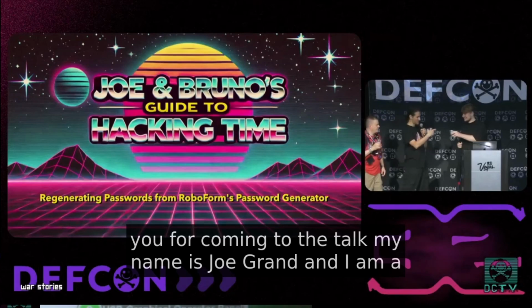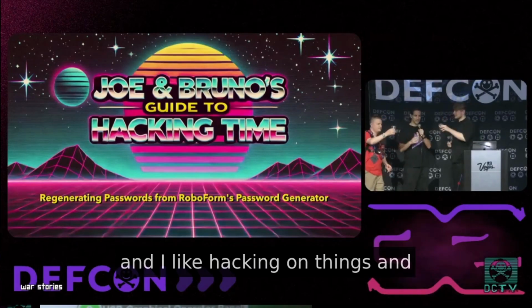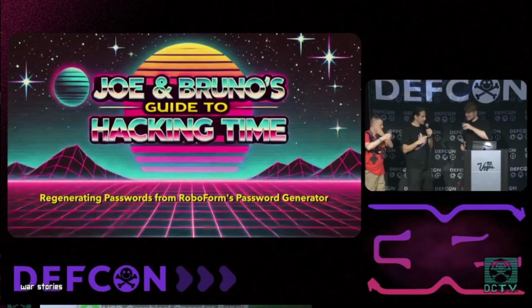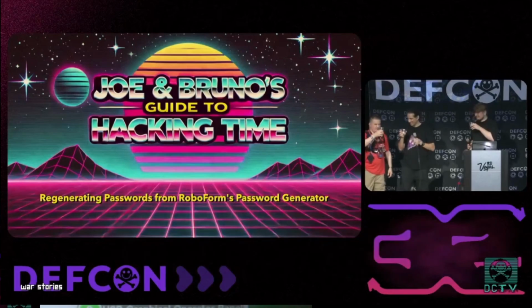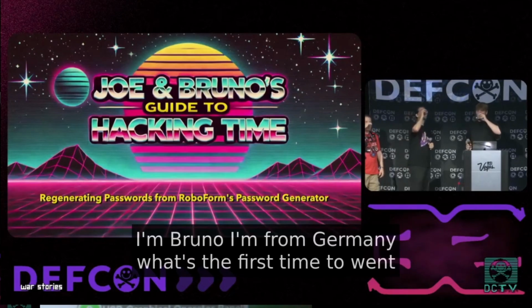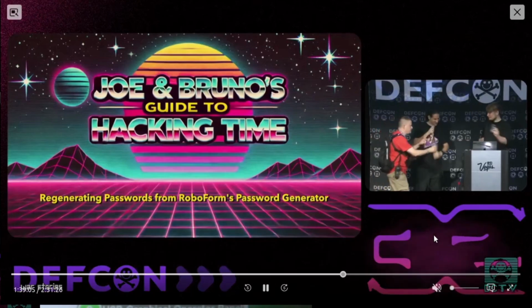First, the sound card can only listen to, say, 48 kilohertz or 192 kilohertz. To get away from all that noise, we modulate the laser. We turn the laser on and off 400,000 times per second. So we're at 400 kilohertz. So we need something other than a sound card that can actually accept this.